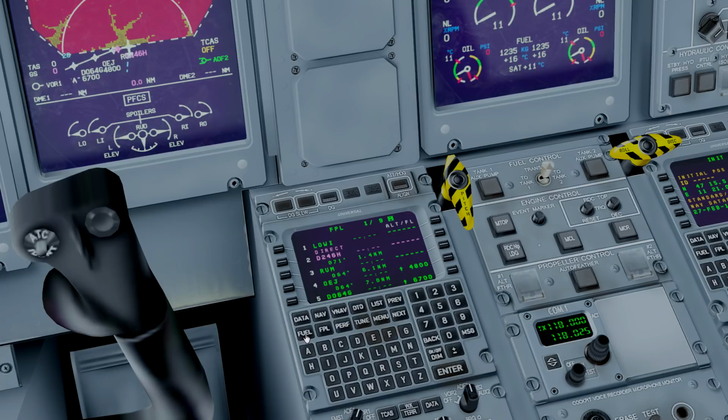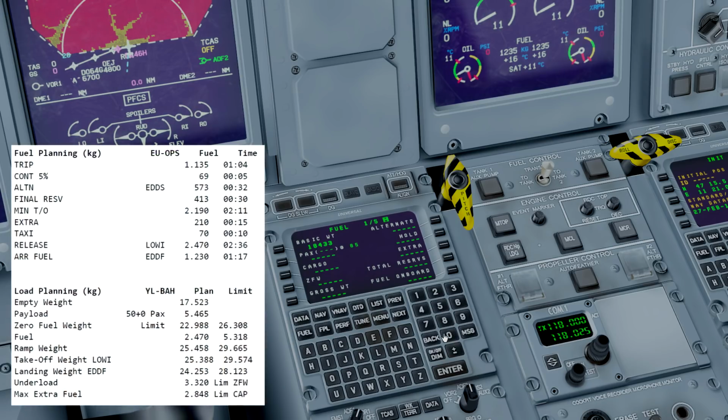Now what we want to do right now is, now that the flight plan has been filled and the entire route is in there, we want to enter some weight and fuel information as we loaded it into the aircraft. So basically, you have here the basic weight, so what the aircraft weighs itself. Then you can enter the amount of passengers. Again, just make sure right here.